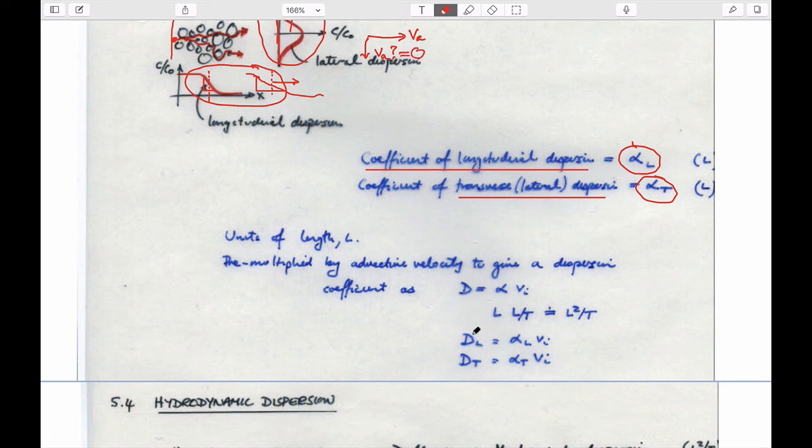So we can get the longitudinal dispersion, which is just the product of this property of the porous medium multiplied by how quickly the flow occurs. Double the flow velocity, you'd get more dispersion because you'd have more mixing occurring. The transverse behavior works the same way. This is a material property, and this is the flow velocity you find yourself going at.